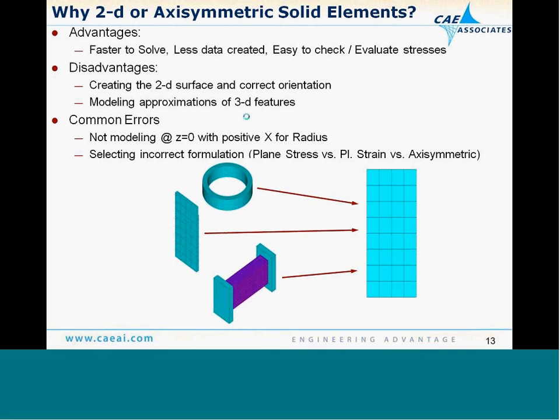And the mesh is just a simple 2D geometric mesh, but depending on, again, the key options we set, this could represent an axisymmetric structure, it could represent a plane structure, or it could represent a plane strain or infinitely thick type structure.